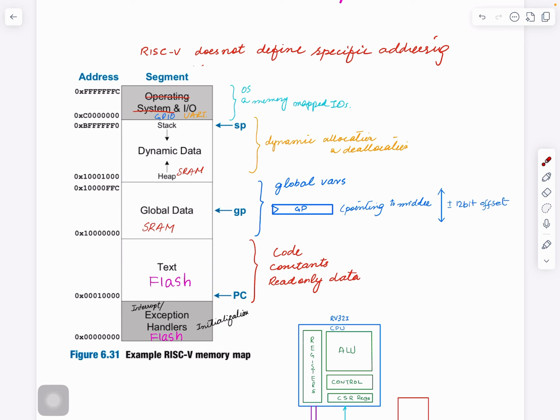Okay, then this is our address space. This doesn't mean that our SRAM is this. By the way, if you convert all these addresses into bytes, it becomes about 4 gigs. So the maximum number of addresses that we can have, or data we can have, is 4 gigs. But it's not all memory. I think this is the point I want to clarify, if it's not clear: these addresses don't mean this is all SRAM. We can make it all SRAM, but it's not.